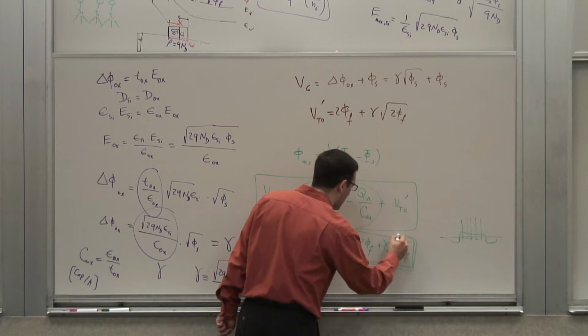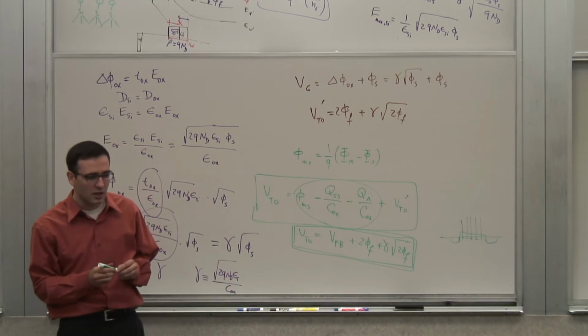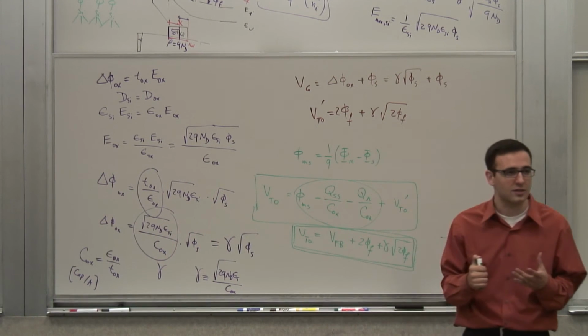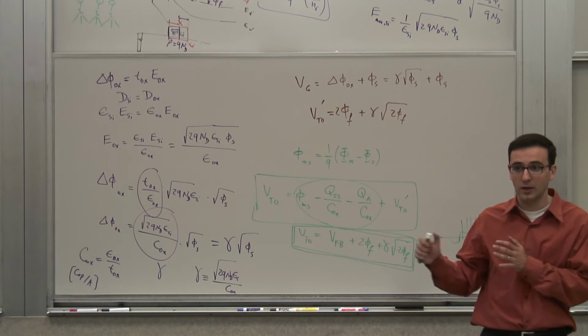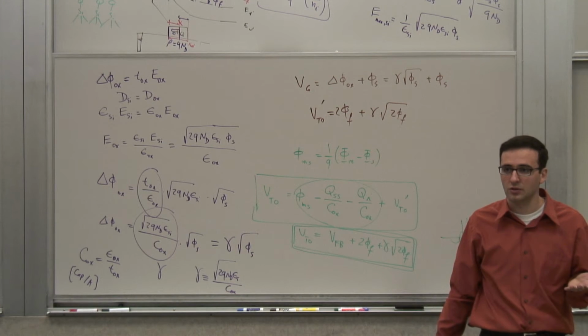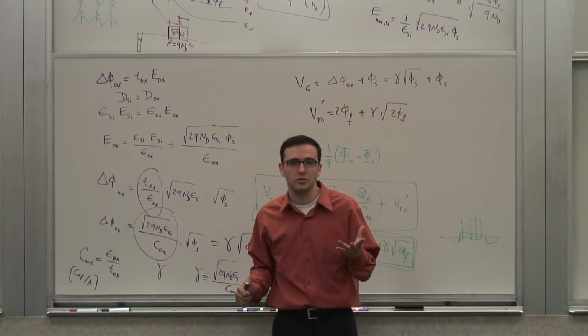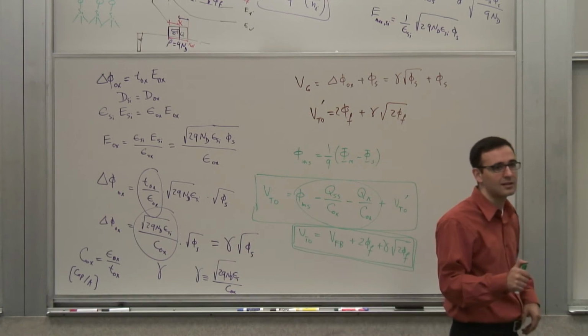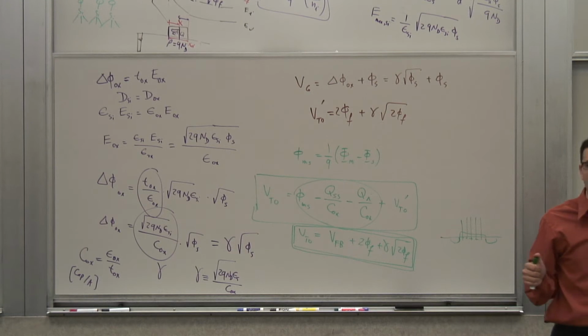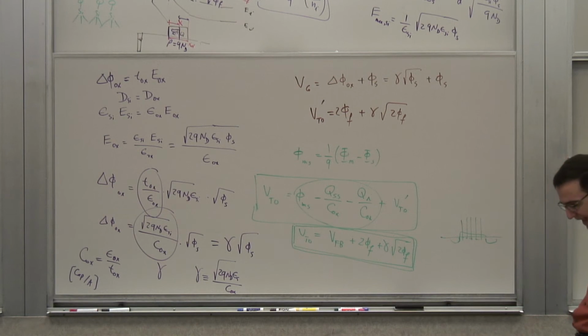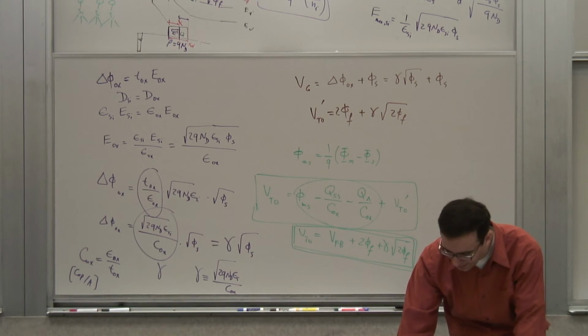This is the minimum voltage on the gate that you need to induce inversion charge, strong inversion, at the surface. It doesn't mean that below this voltage you don't have any inversion charge, right? We know we do, and that's the cause of sub-threshold current in MOSFETs. We'll talk about it a little bit later. But other than that, that's what I need to induce strong inversion at the surface.